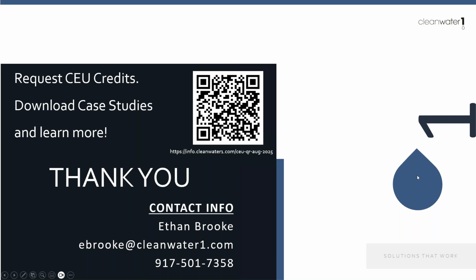All right. So what are the Henry's Law coefficients for water if it's just 10 degrees C, cold water conditions? Great question. Henry's constant is definitely affected by temperature. The colder the water, the less volatile, or the lower the Henry's constant. This is something that we do look at a little bit during our modeling. But recall, we can strip the brominated species no problem with very low Henry's constants. It's just a matter of how much air we need to introduce.